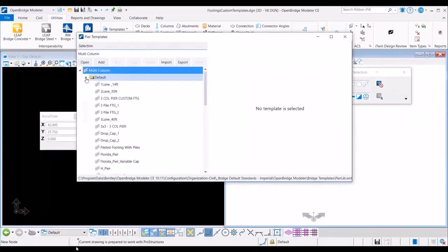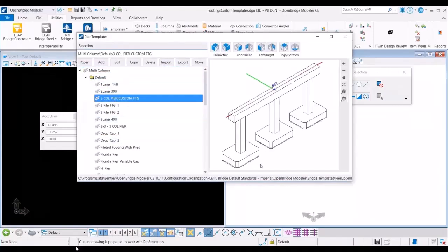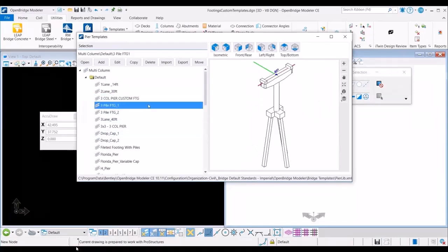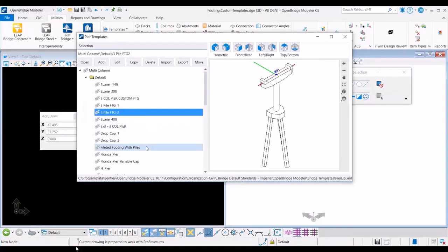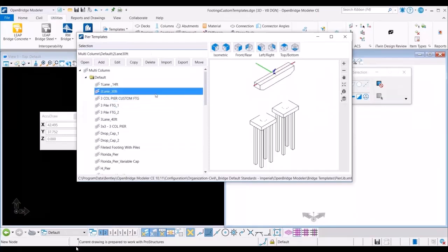customize that. I just created a template, remember that. So I have different piers here. This is the one that I use, right? So how to specify that I want a custom pier rather than the one that comes with the dialog box itself, right? So we enhance the libraries now, so you can make copies of it. But then let's edit that internal file to see how you add this custom template for you. So I'm going to copy one existing one that does not have this custom template. I'm going to make it custom for me.